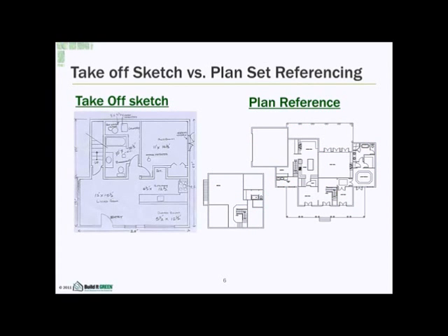Okay, so takeoff sketches on the left, you can see this is actually a really good takeoff sketch, but typically takeoff sketches won't really need interior partitions or any of the appliances, but a fine level takeoff will have almost everything noted, and wet rooms and dimensions. But with your multifamily buildings, it will take you a very long time to draw the building, so you can most likely leave this information out.